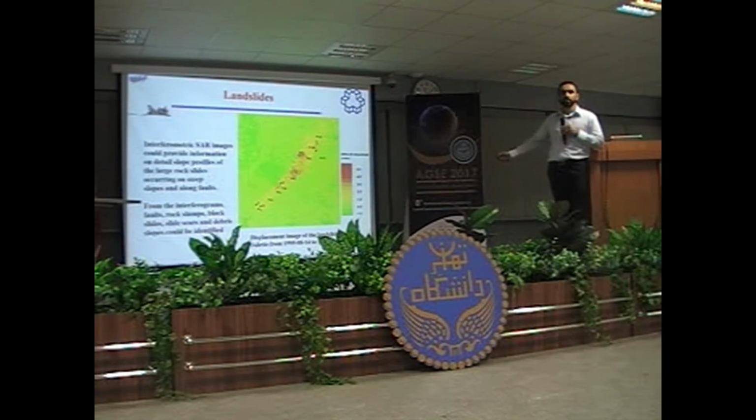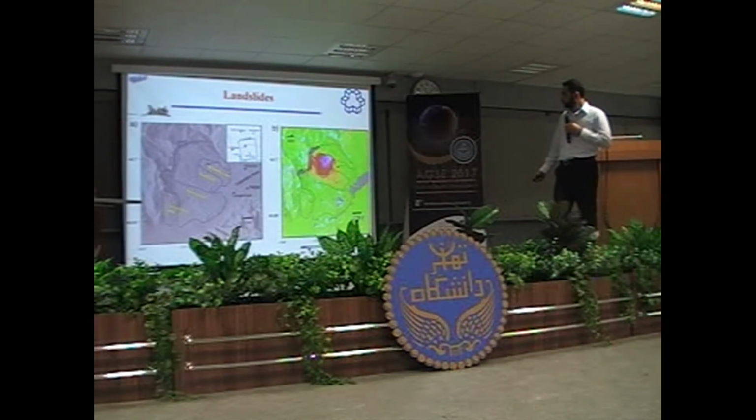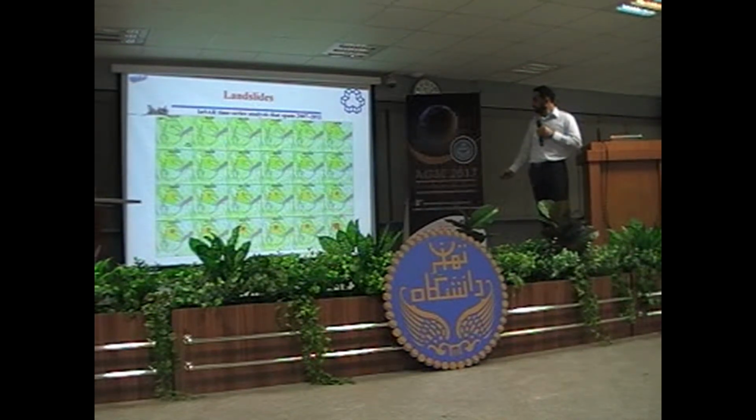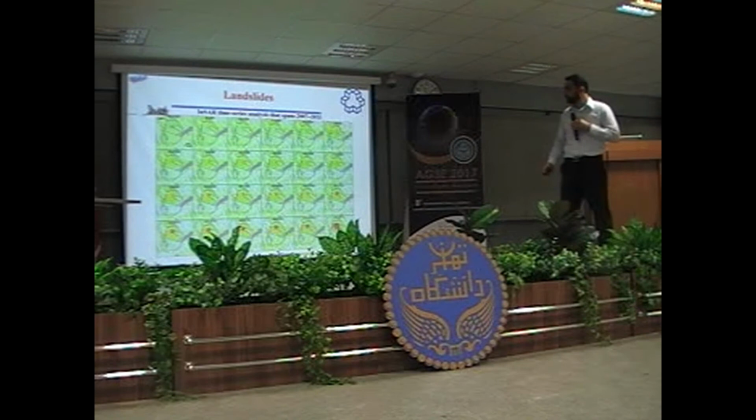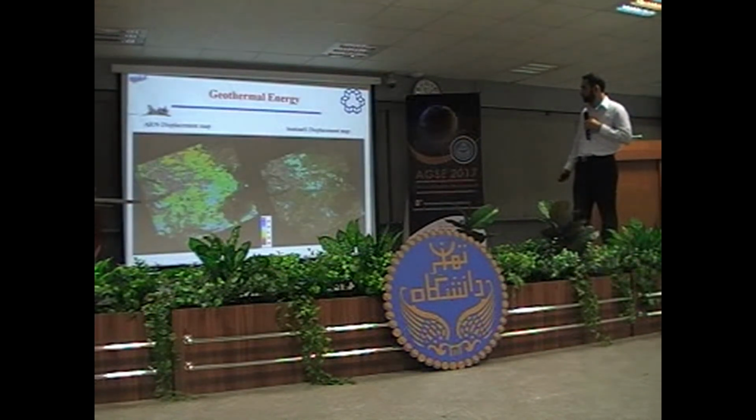We have landslides. For landslide monitoring, interferometric SAR is also very useful. The amount of landslide between two images can be quite clear in this image. When it is negative, it is subsidence; when it is positive, it is uplift. And you can monitor this landslide at different times. See, the landslide starts at this date, and then the amount of landslide increases to one point, and then starts to decrease. So this kind of information can easily be obtained using interferometric SAR technology.